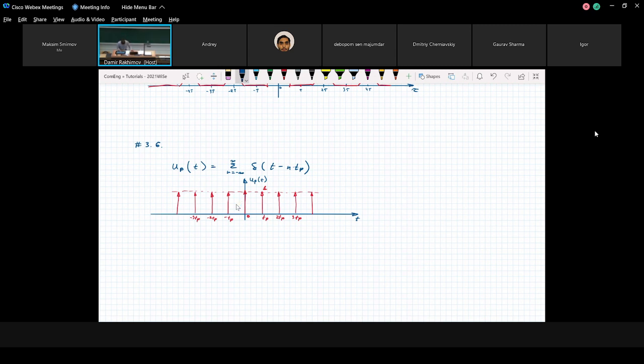So we calculate the Fourier transform. We're going from the time domain to the frequency domain. And again, we plot. Before we plot, just look at our table of basic transforms, and we see that if you have an infinite sequence of delta pulses, after Fourier transform you get another sequence of delta pulses with different spacing and different magnitude. But you can find them, because spacing will be the inverse of the period in the time domain, and magnitude will be normalized by spacing: the original magnitude divided by the spacing between delta pulses in the time domain.